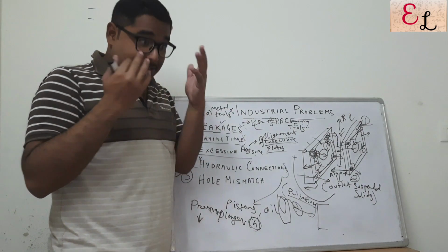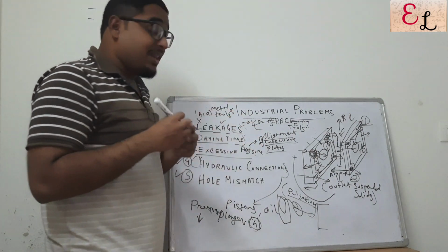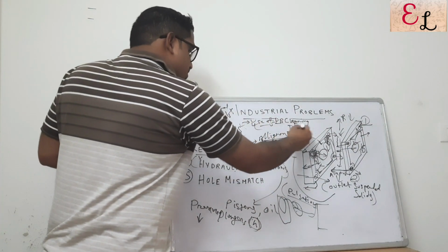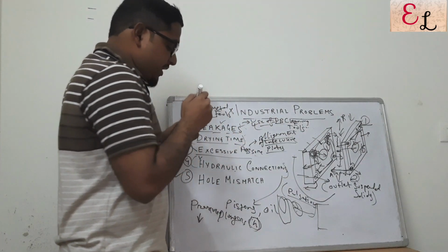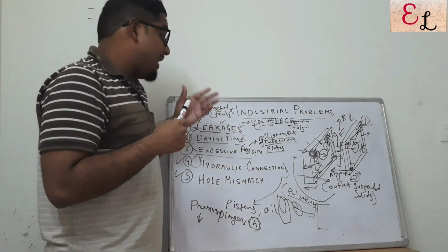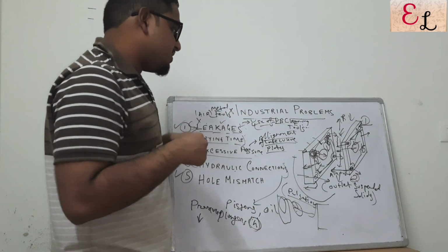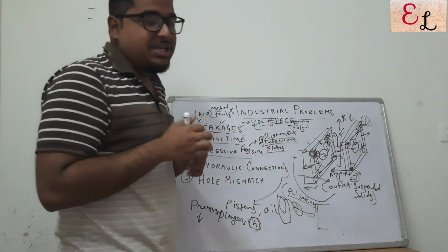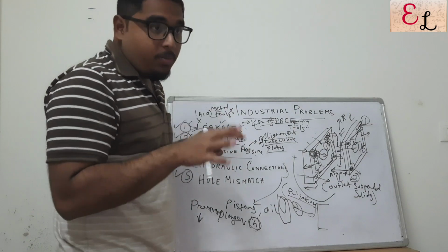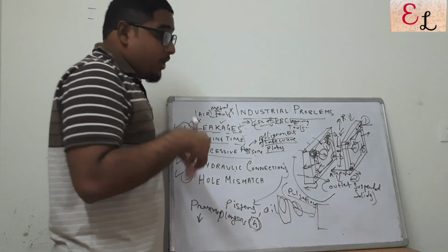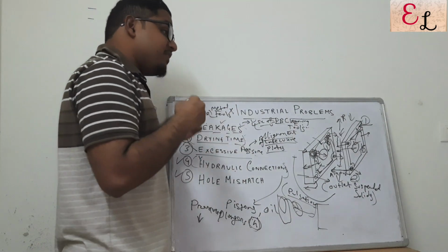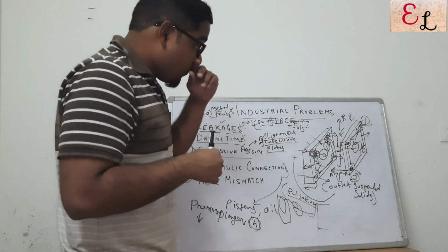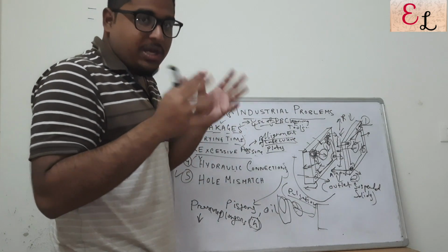Also, PP tools, as we know, are not that reactive and survive acid, so they can be used readily instead of metal tools to clean the cloths, so that when you clean the cloths, you do not cause damage to the cloths themselves. And the application of pressure while cleaning the cloth should be as minimal as possible. It should fall by itself. Instead of using a metal tool, you should ensure the cake falls by itself, because if it doesn't, then you need to apply pressure on the cloth, and that is not very good for the health of the cloth, because that causes wear and tear.